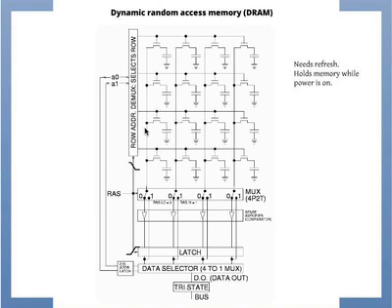Dynamic random access memory is a little bit different. It's a much simpler configuration. So you will see that DRAM is cheaper than the SRAM, typically. Okay. The idea is much simpler. All you do is you basically have a transistor attached to a capacitor, and the capacitor holds some charge. Lots of charge there means 1, if you have 0 charge there, it means 0. That's basically it. And all you do is turn on this transistor and you access the charge here.